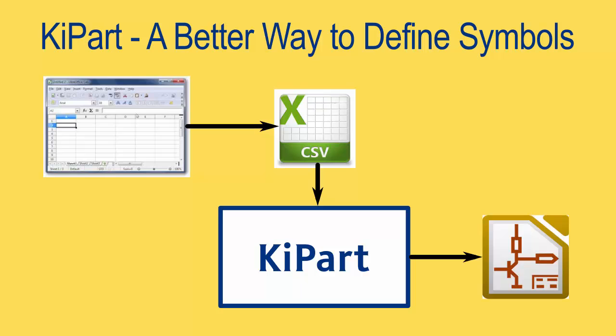Now I want to talk about KiPart, which is a better way to define KiCad schematic symbols. First of all, pin data will be entered using a spreadsheet, which is fast because that's why spreadsheets exist. The pin data will also be visible, so it'll be easier to spot errors. The spreadsheet will store the pin data in a CSV file, comma-separated values. This CSV file will be the input to the KiPart command line program. KiPart will translate the CSV file into a KiCad schematic library. Because KiPart is a program, it's fast. It also does the same thing every time, so the schematic symbols in and across the libraries it creates will all be consistent with each other.